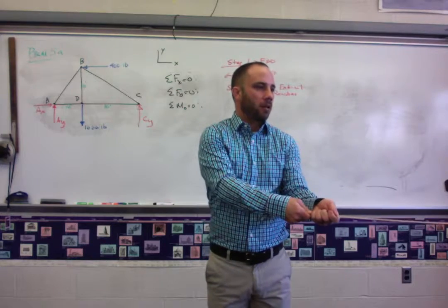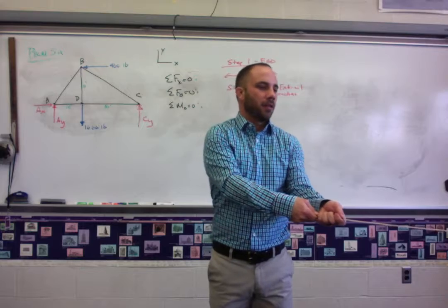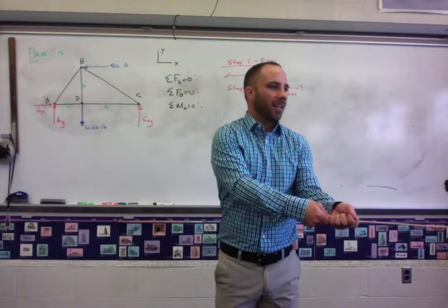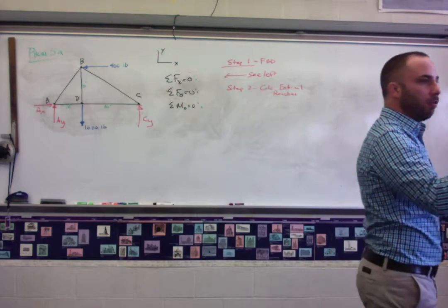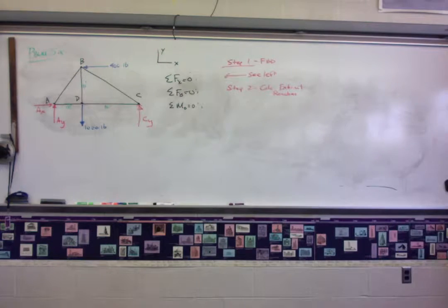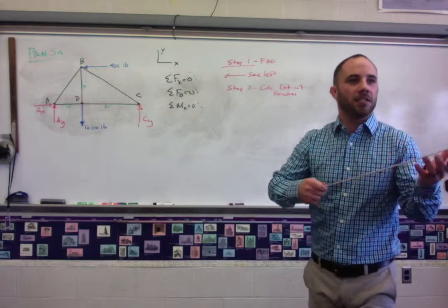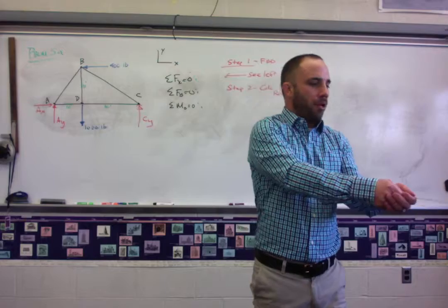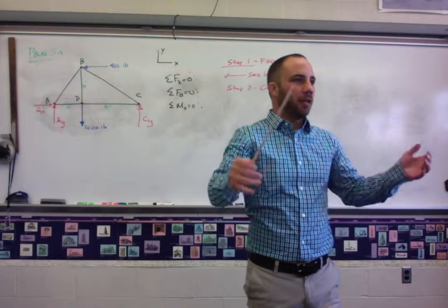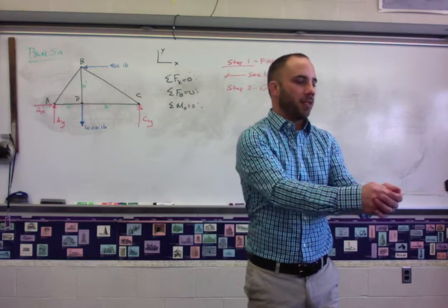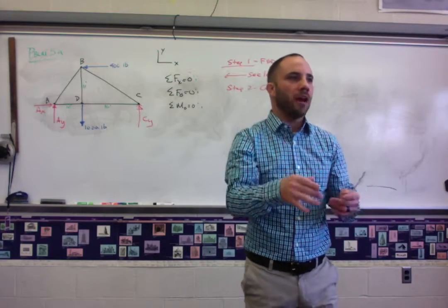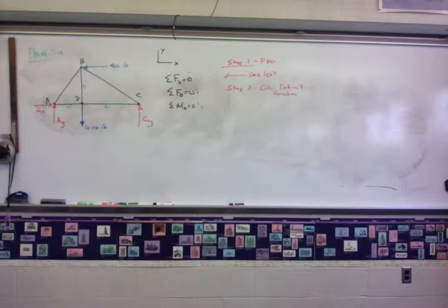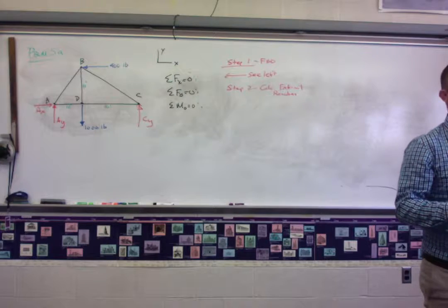Grab it with 2 hands. Try to pull it right from the middle, see where it breaks. Only a tensile load. It's almost like a cable. Yeah, it broke again. That's all right. There was a force there when it broke. So, indeed, it was a tensile force. Now, if we make this a compressive force, and we push, it buckles really, really far before it actually breaks. So, it's just breaking in the middle. It's buckling. It's called lateral buckling. Those are internal forces.